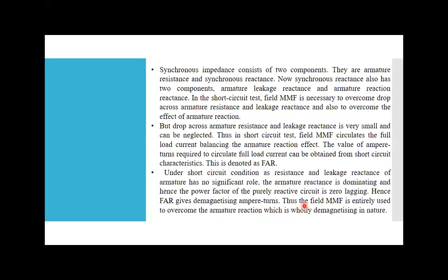Generally, most of the time my load is inductive in nature, so my power factor is lagging. You can take any case, they always give you a lagging power factor, because 90% of our load is inductive. We do not have purely resistive or capacitive loads. We have loads that are a combination of RL, so it is inductive in nature. That's why my armature reaction effect is demagnetizing in nature.